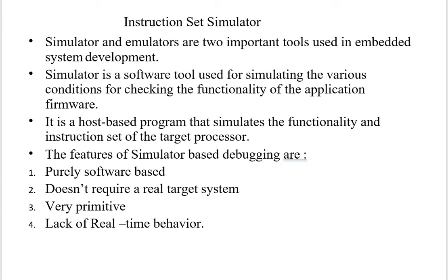Instruction set simulators and emulators are two important tools used in embedded system development. A simulator is a software tool used for simulating various conditions for checking the functionality of the application firmware. It is a host-based program that simulates the functionality and instruction set of the target processor.